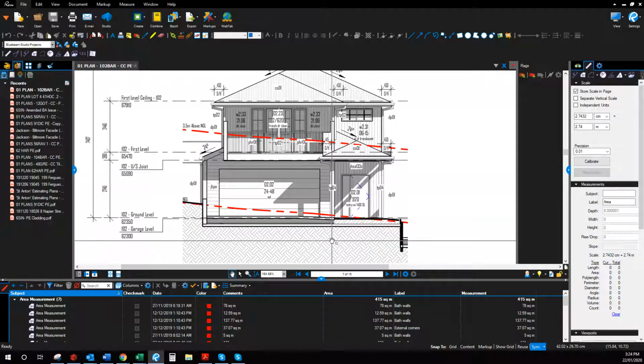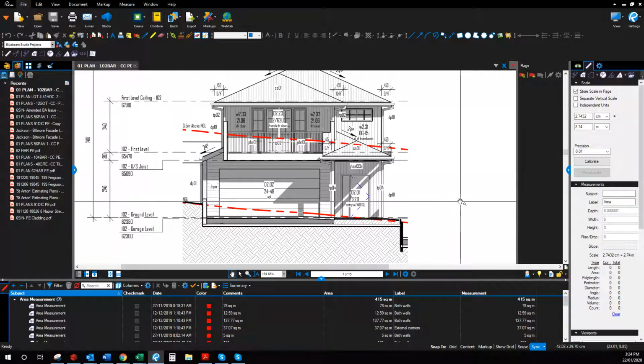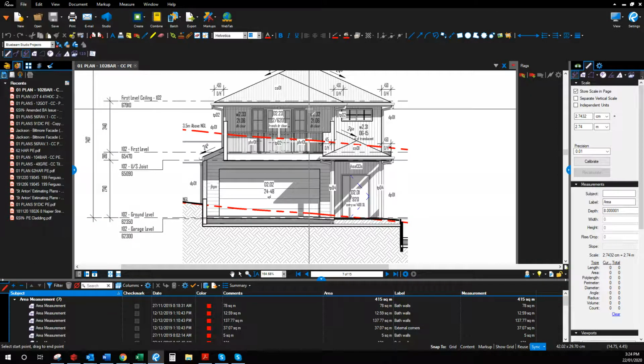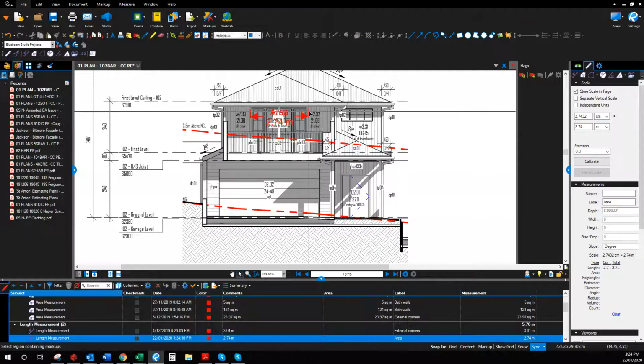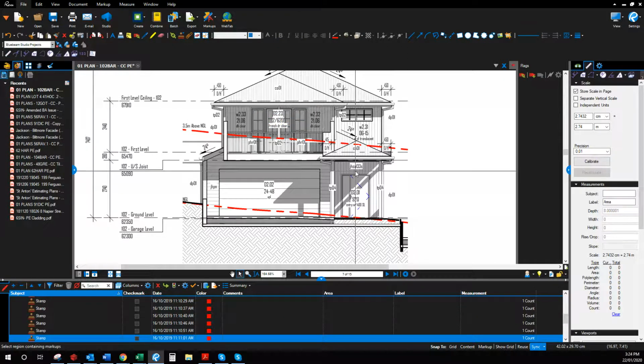For this, it's basically a square meter takeoff where we only remove openings over 3 meters. As I go around, you'll see how I make that 3 lineal meters. Like this fairly large section of door here, I can't take it out. It's not more than 3. It's a bit of an odd rule, but that's just the information they gave me.